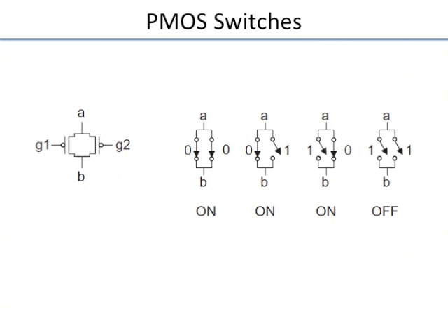based logic is important. Why? Because when someone tells you, okay, implement this particular function in a CMOS gate, that will be a question for you in one of the quizzes. So I'm telling you right away. Okay. So how do you do it? So you basically find out the switch network for the NMOS. Once you find it for the NMOS, for the PMOS it is just the dual of it. Okay, and then you put the two together and just cross check your answer always. Especially the truth table, just see if, when you put in those values, you are getting the right outputs or not.